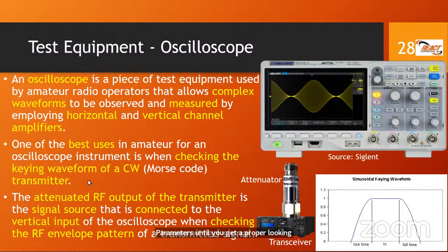All right, so another exam question. If you're going to use a scope like this to measure your RF output from your transceiver, you do not connect it directly to your RF output. You will destroy your oscilloscope. Oscilloscopes are very sensitive. These terminals here, these BNC connectors as they're called, have a limit to the input in terms of the voltage, right? And there's actually a warning here that tells you that.